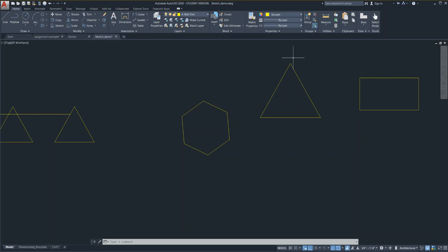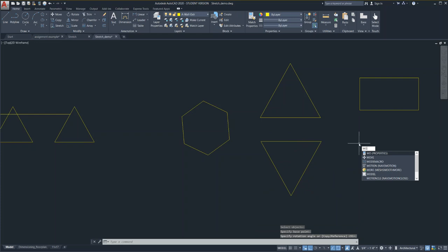Okay. If I needed to create a second triangle, right, that's upside down so that I could create a star, I could do that, rotate it, right? I could CO, copy, enter, copy it down, RO, enter, rotate, enter, click the middle, rotate it, right, MO, move.